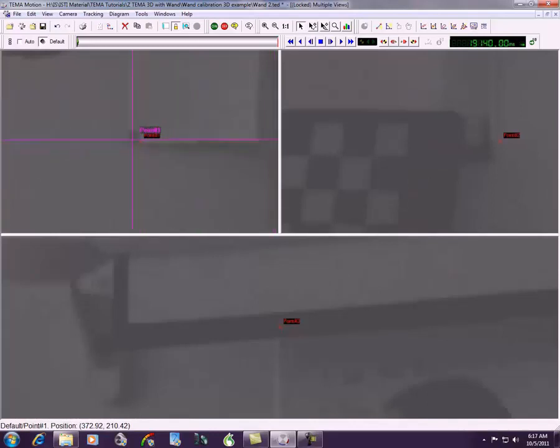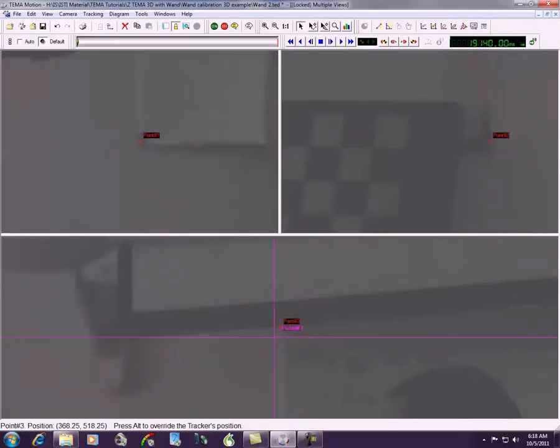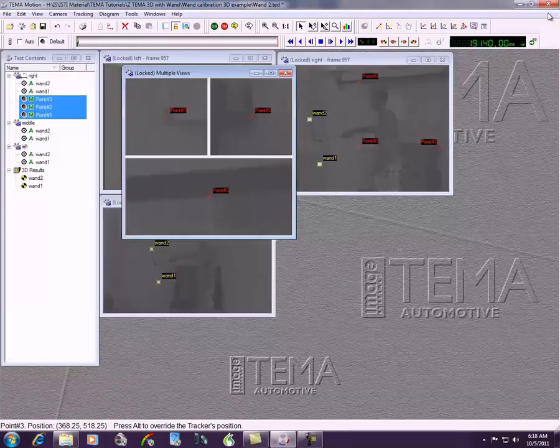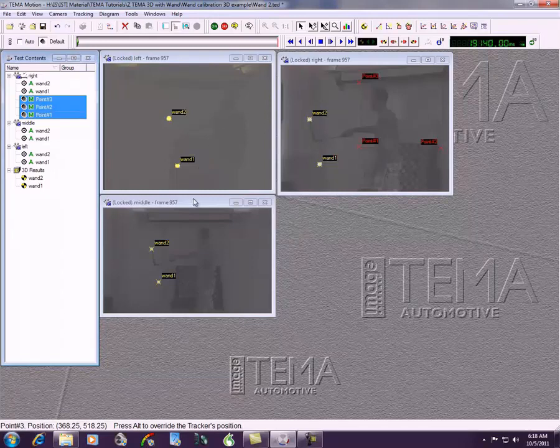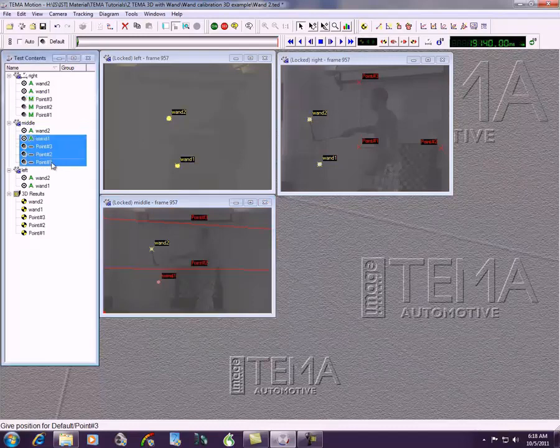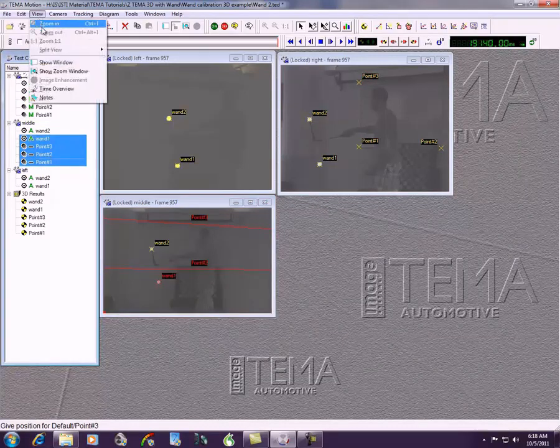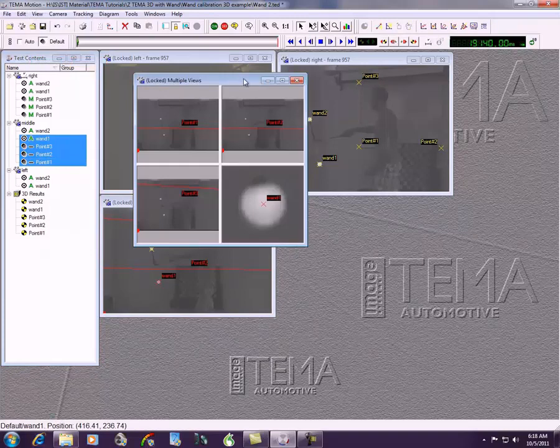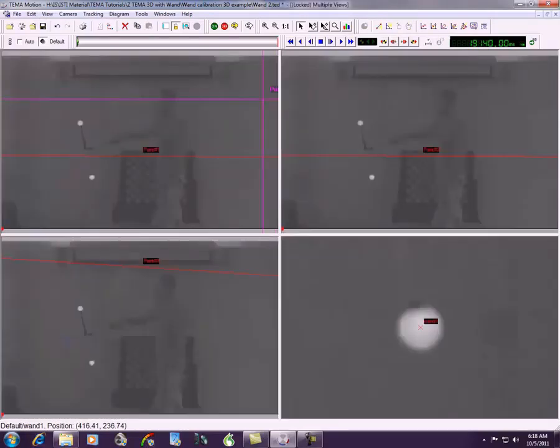We will use the show window to get an accurate position for each of the points. When we add these points to the next image, TEMA will draw a back projection line showing the places on which it expects the points to fall. We will have to confirm the point location. The accuracy of this prediction is an indication of the accuracy of the 3D analysis.